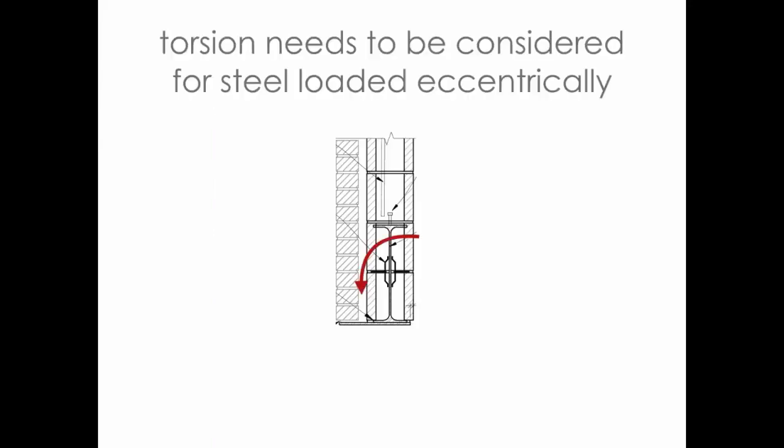And so these are the challenges that we get faced with. We're solving one problem, and we've created a couple already, right? That we have to look at how are we going to solve this. Just creating the cavity wall scenario with a steel lintel. One, you have thermal bridging. We'll maybe get to that in a little bit if we have time.